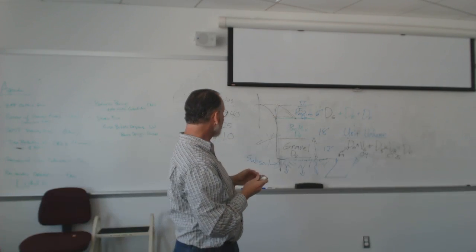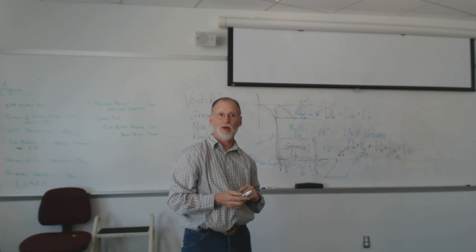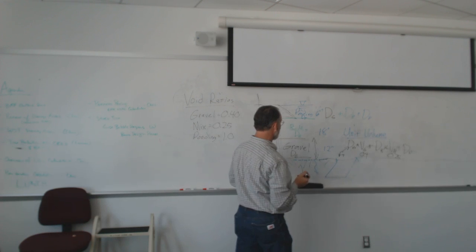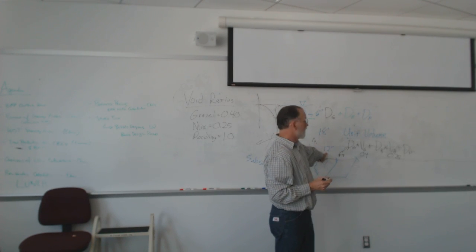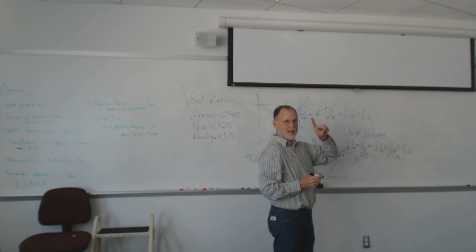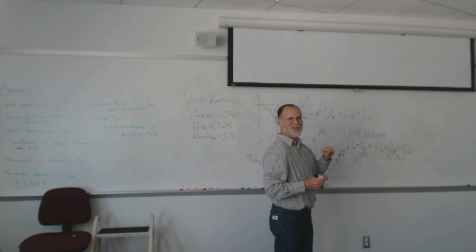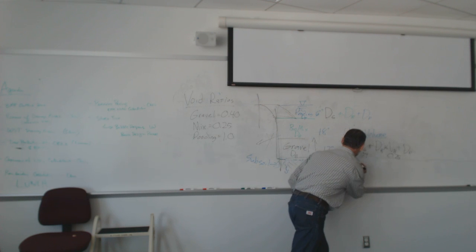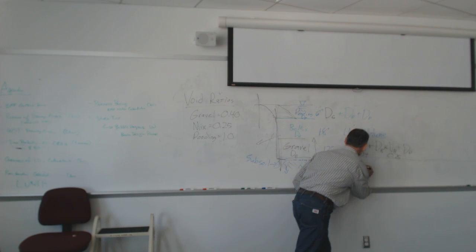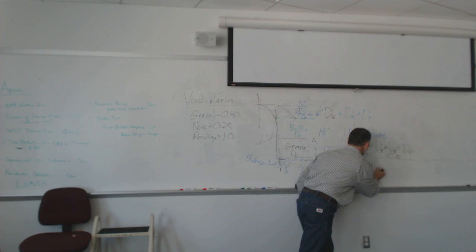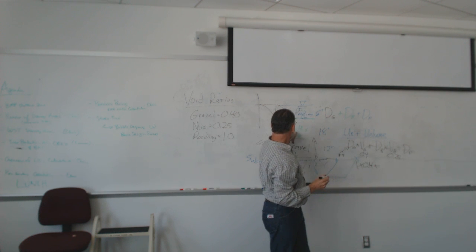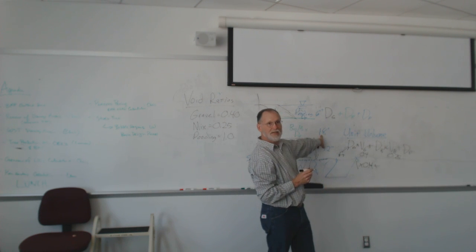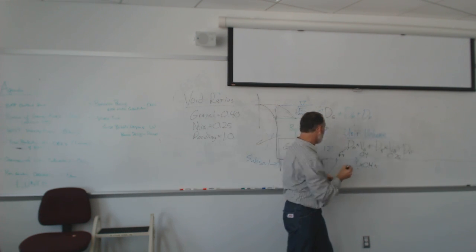Okay, so here's how that works out. Let's just use the numbers I already wrote on here, and somebody with a calculator help me out. We've got 12 inches of gravel, so we convert that to feet, so that's 1 foot. I can do the math for the first one by myself. That's going to be 1 times our void ratio, 0.4. Does that make sense? Then our depth for our biomix in feet, 18 inches, is 1.5 feet.